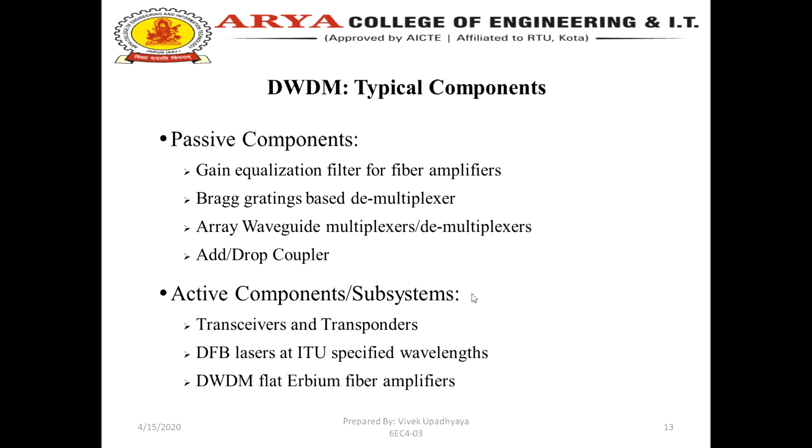Active components or subsystems are the transceivers and transponders, DFB lasers at ITU specified wavelengths, DWDM filters, and EDFA, erbium doped fiber amplifiers.